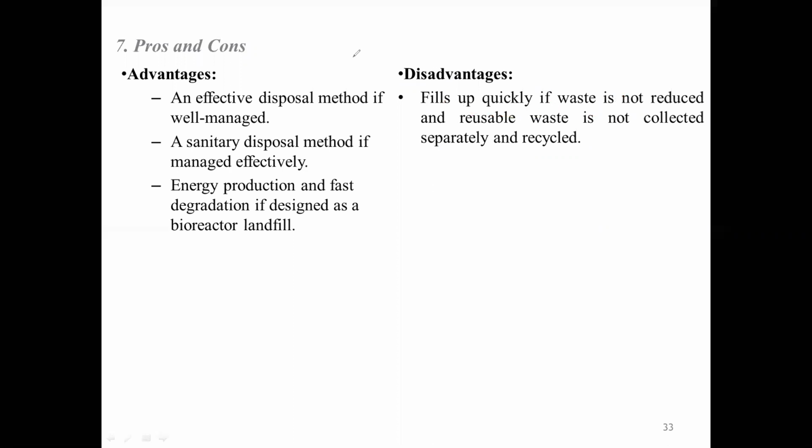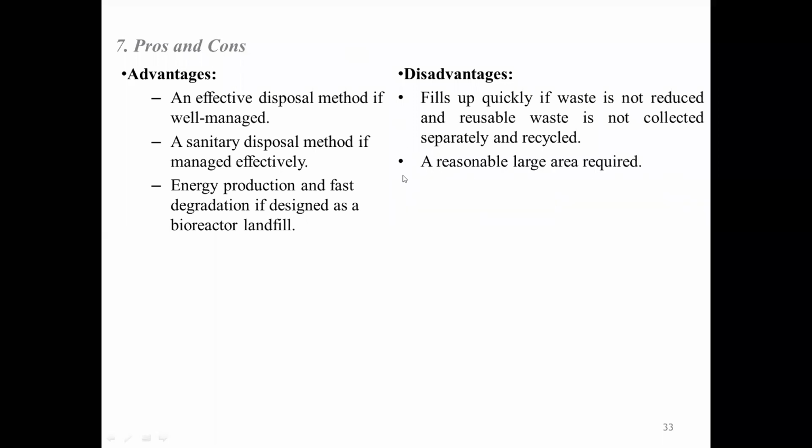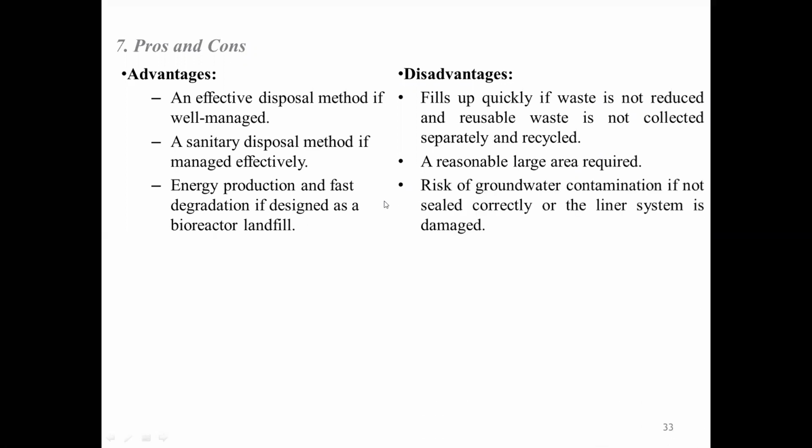If one landfill fills up quickly, then you have to search for another landfill, and you require a larger area for disposal compared to other systems, right? If you're not sealing, of course, there is always a chance of groundwater contamination of soil and water if the liners are damaged at any point during the complete disposal process.